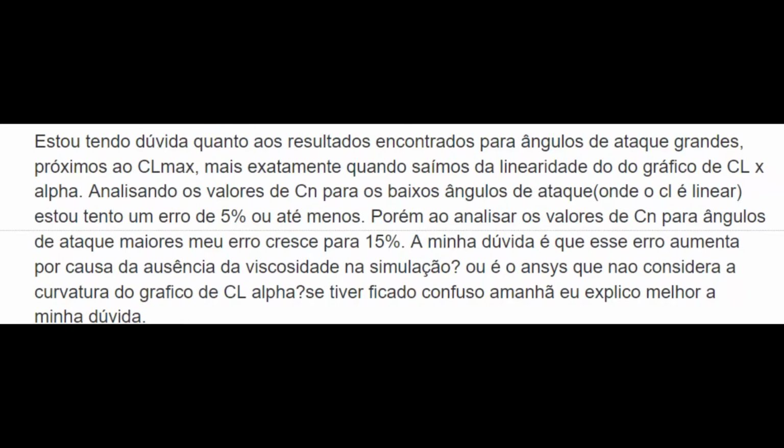Okay, but since the airfoil is a streamlined body, when the flow is going smoothly around the wall, we expect that K omega or K epsilon model are suitable for this kind of problem, and they will result in a much better precision.